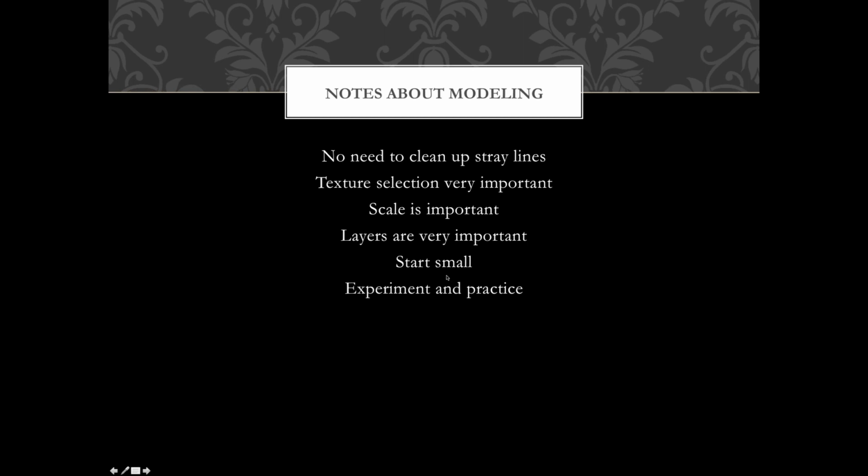Start small, and that goes for when you render. You want to start with a small resolution when you do your test renders. For example, if you double your height and width on your output image, you have 4 times as many pixels, so the computer takes longer to render it like that. So you start small, and then once you have all your materials set up, then you do your full-size render.